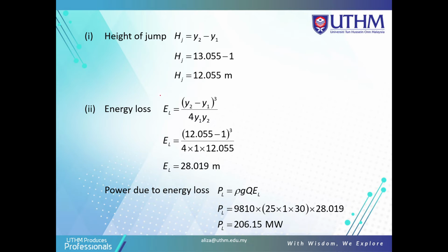And then you find the height of jump. Using this formula, y2 minus y1, you get the value of 12.055 meters. Then using the formula of energy loss, you get EL here based on the energy loss formula.